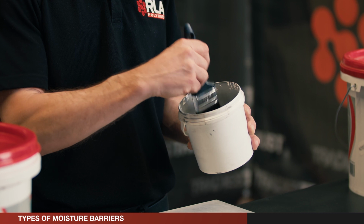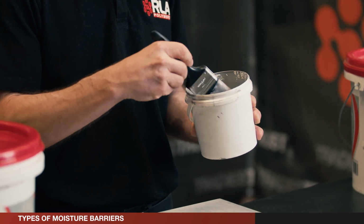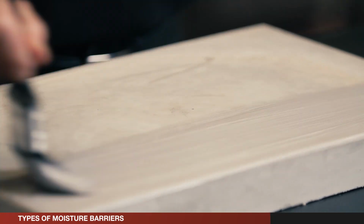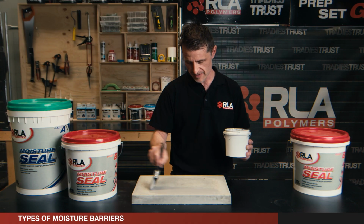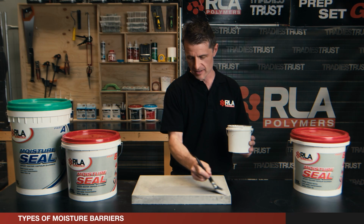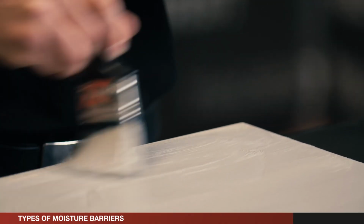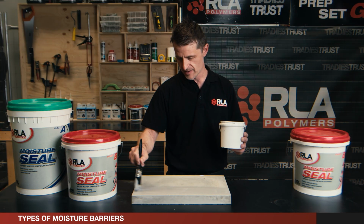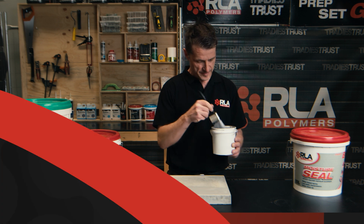It's basically applied just by brush or roller directly onto the substrate, and as I said, in a couple of coats. Goes on quite easily, just like a thin paint type coating. Just brushed evenly and neatly onto the surface. Allow it to dry between coats, and 24 hours later, you can apply the floor finish over the top.